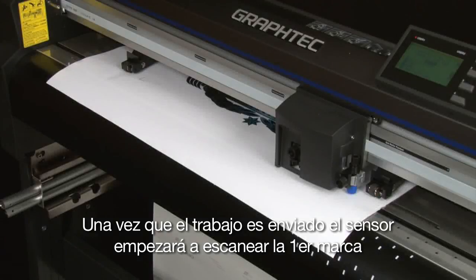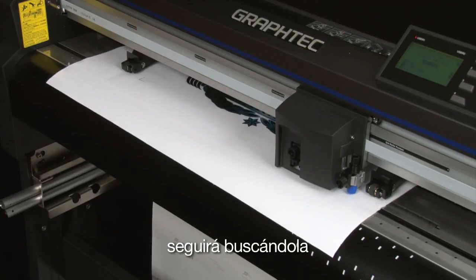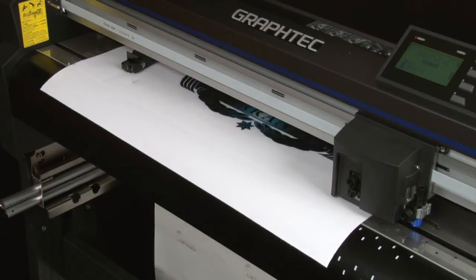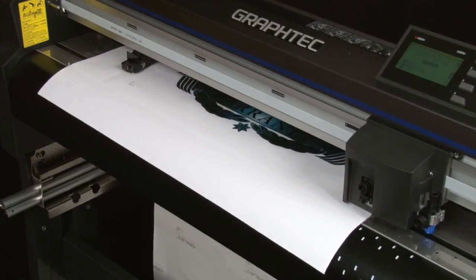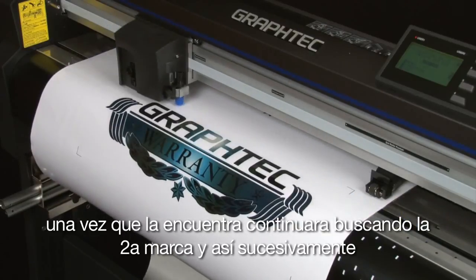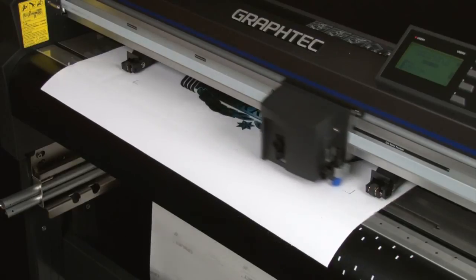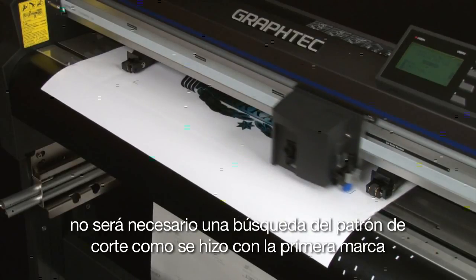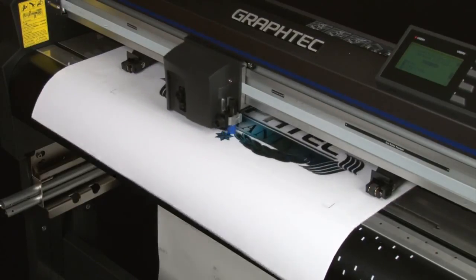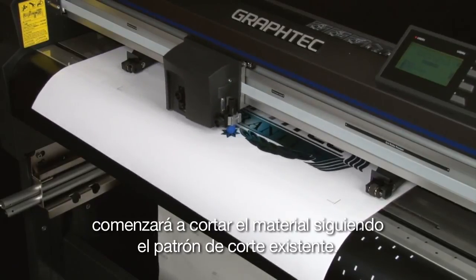Once the job is sent, the sensor will start sensing the first mark. If for some reason it cannot find it, it will go searching for it. Once it finds it, it will continue on to the second mark, and so forth. Since it knows the location of the other registration marks, it doesn't need to do a search pattern as it did on the first registration mark. Once all the marks are found, it will start to cut the media following the adjusted cut path.